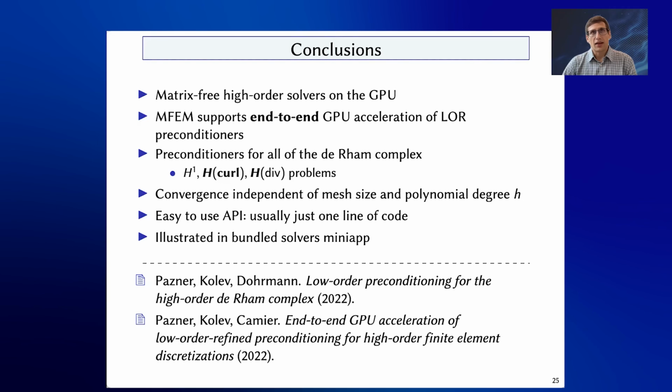So the vertices of the lower order refined mesh are at the Gauss-Lobatto points in the coarse mesh, and the way that this works is that the values of the coefficients will be evaluated exactly at those Gauss-Lobatto points. So it basically takes the Gauss-Lobatto integration rule on the coarse mesh, evaluates the coefficients there, and then uses those in the assembly routines, interpreting those nodal points as the vertices of the lower order refined mesh.